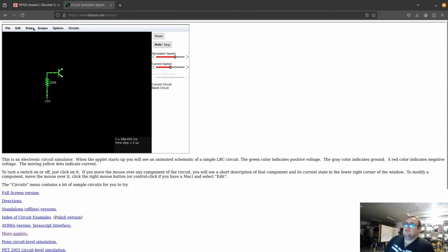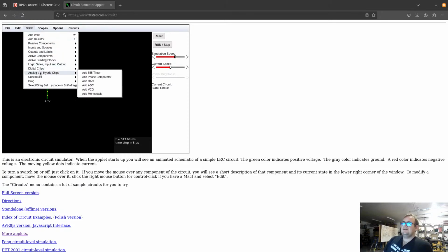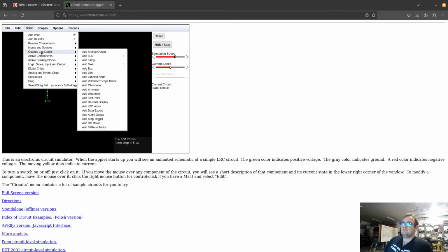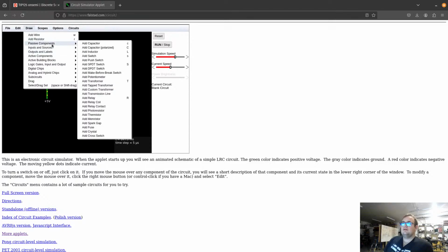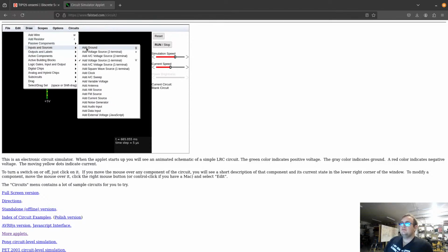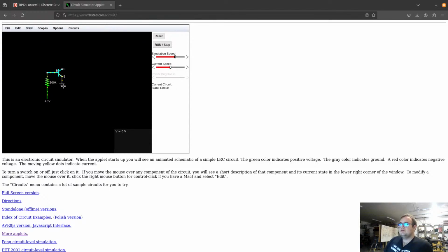Yeah, then we'll just draw a ground. What's the sources? Ground. Yep, 22.4 microamps it says. Because there is about 1 diode drop here, so about 0.6 volts of a diode drop.